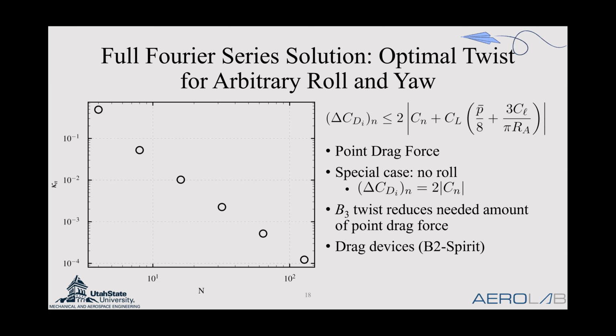That's all that will tell you. So it is beneficial in that sense to know your max authority, but for any condition away from the max yaw setting, say you only want to implement 10% of your yaw capabilities, you want to be able to do that optimally, and by optimally we mean with the least amount of drag possible.